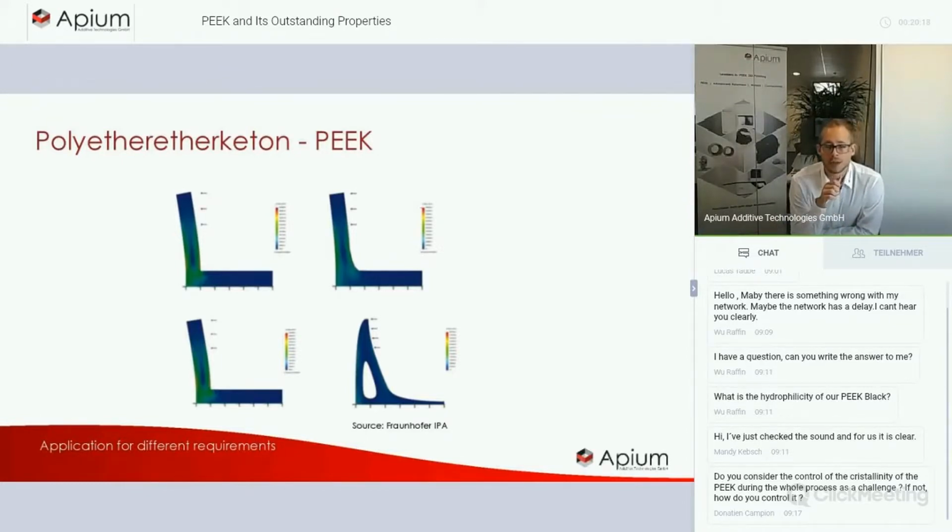The corner at the top left is a 90-degree corner. And we see with the top right part, if we smoothen out this corner, so that we don't have 90 degrees but a smooth transition from these perpendicular surfaces, we can already see a decrease in the stress that is working